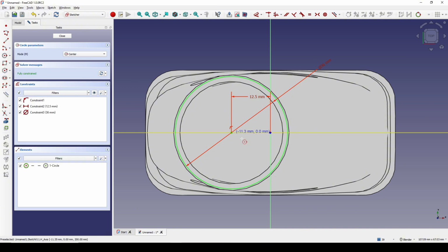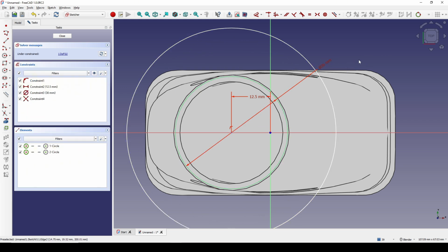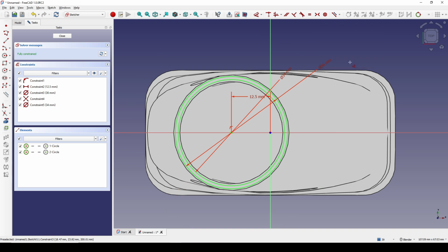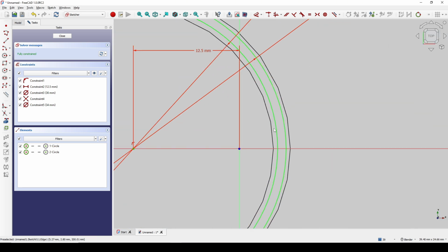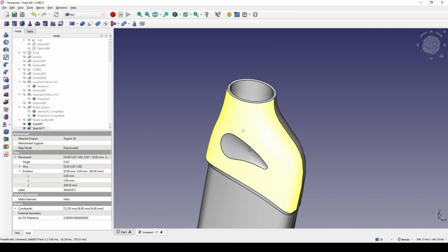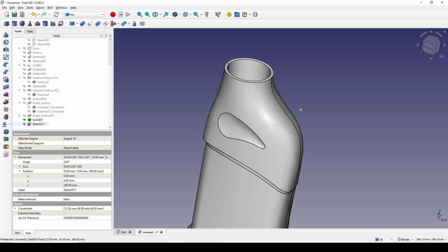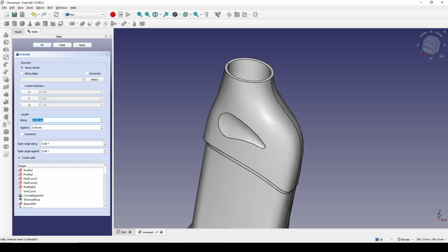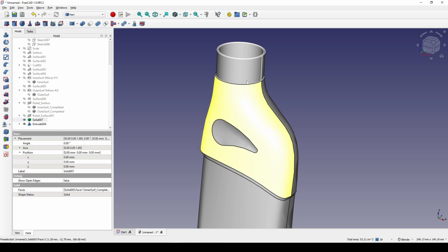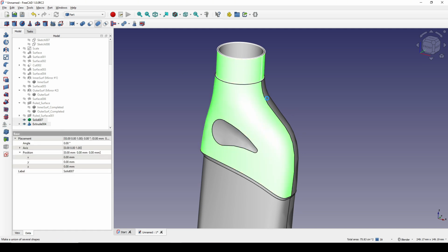And creating another one also in the center. Go out, selecting this circle and hit D and set the diameter to 34. So you can see the new circle also inside here, and then I close. Next, I select this sketch and go to extrude. Let's extrude this one up to 20. Okay. Now I control select the solid and the extrude, and I union them together.